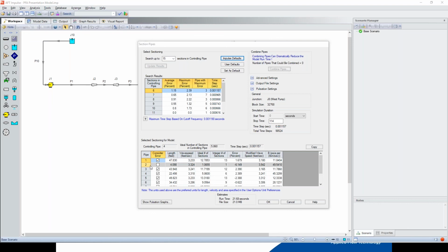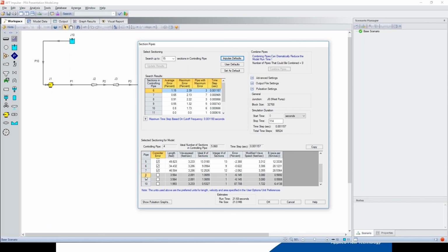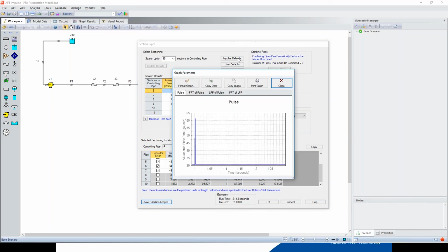Then we specify the pulsation source. We said that it was a positive displacement pump, number of heads 5, 250 RPM, and buffer of 12. And finally, we have the low pass filter that is calculated for us. So not all the high frequencies will be analyzed, and it sets the 140 hertz that is established based on the pulsation source that we defined. Finally, we go to the tab with the PD pump settings, and here we specify all the characteristics of the pulsation setting